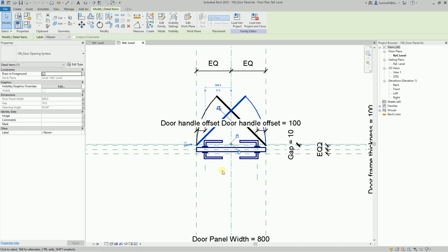If one of these nested families is more complicated than the others, and we need more parameters there, then you will still have to create the same parameters in less complex families, even if it's not necessary for it. Otherwise, the program will give an error when replacing one nested component with another.